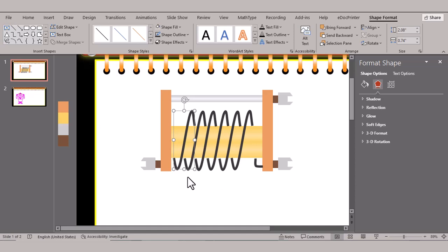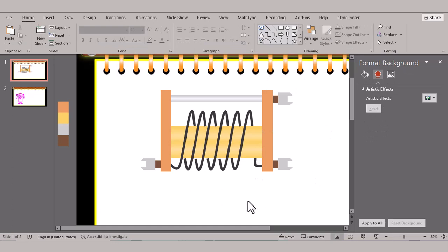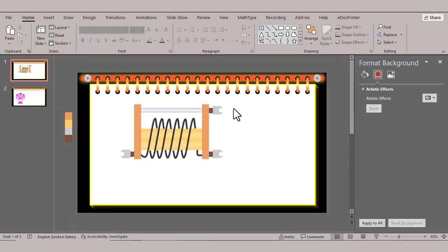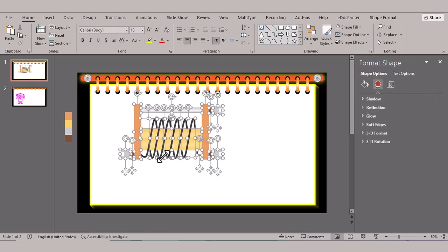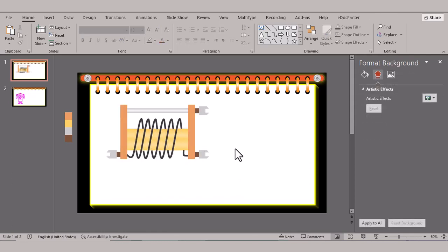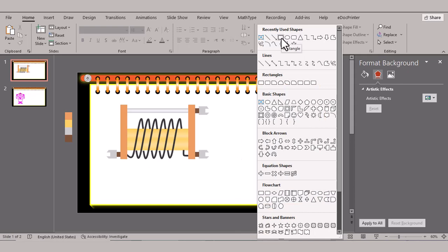The ohm is the common unit of electrical resistance, equivalent to 1 volt per ampere and represented by the capital Greek letter omega, Ω. The resistance of a wire is directly proportional to its length and inversely proportional to its cross-sectional area. Resistance also depends on the material of the conductor. The electrical resistance of an object is a measure of its opposition to the flow of electric current. Its reciprocal quantity is electrical conductance, measuring the ease with which an electric current passes.